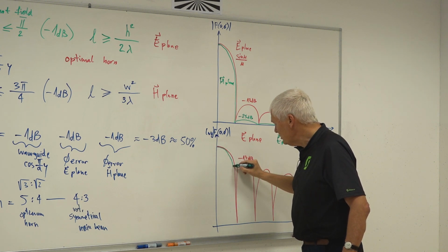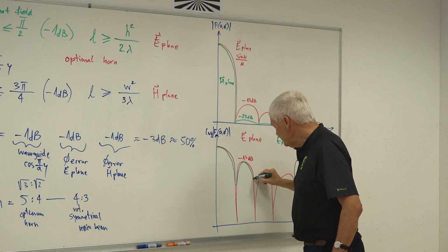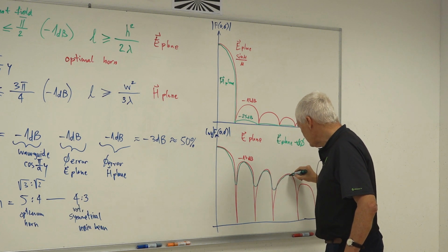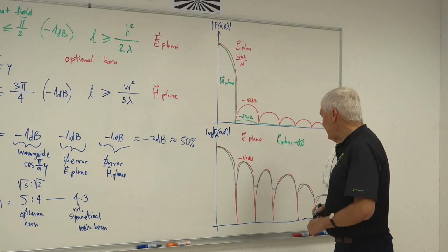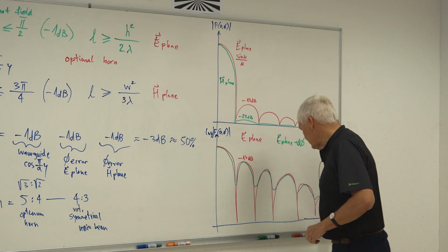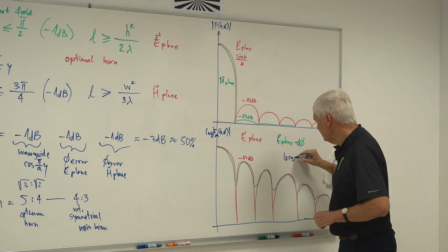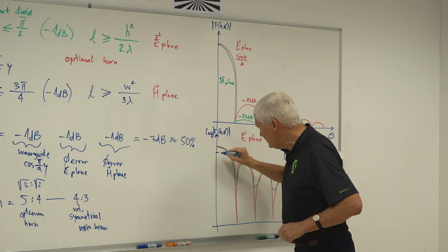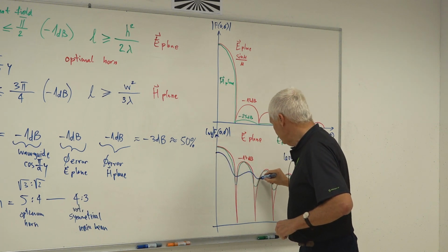The radiation pattern, only the minima will become shallower. But the radiation pattern, you simply don't see any difference. Only the minima here become shallower. And only when you have large phase error, then you see some decrease of the main peak, and of course shallower minima.